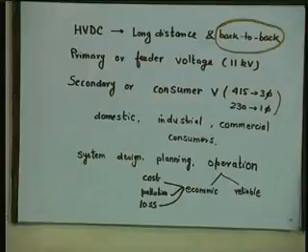also called back to back connection, because you are just connecting two neighboring AC systems. So, this can be in the same building, in fact, that is why it is called back to back. The advantage I already told you, you can connect two systems of different frequencies.